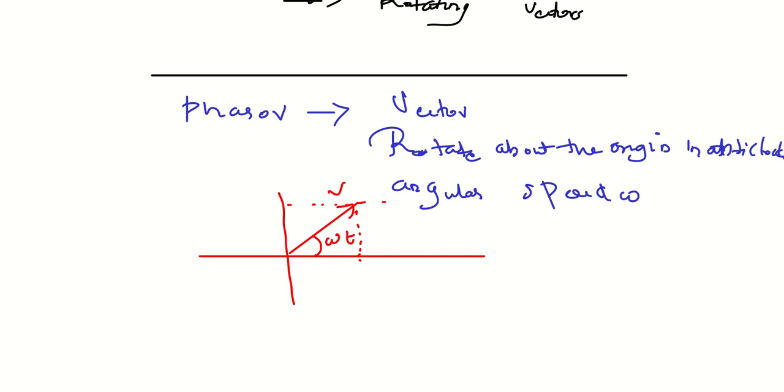So in a phasor diagram we can represent a voltage or current. Here we represent voltage, so the length of the phasor represents the amplitude. Do you understand? The amplitude or peak value of voltage or current is represented by the length, denoted by Vm, and the projection of each phasor on the vertical axis gives the instantaneous value of the quantity that the phasor represents.